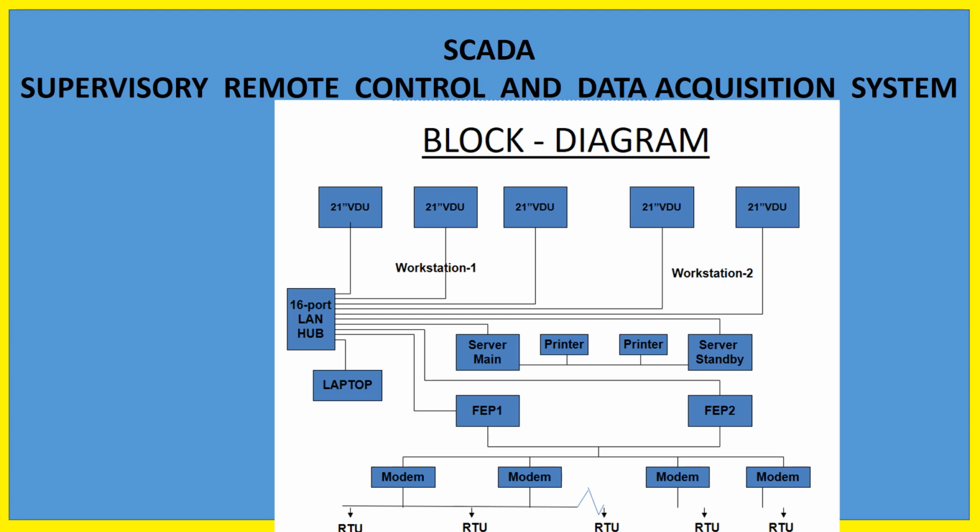This code is a DC signal with little energy, so it cannot travel to the end. So what we will do, we will modulate it with some carrier wave which has good energy, so that it can carry up to the end. After modulation, we'll send it through the OFC communicating cable to the particular post. It will read it by its address, and accordingly it will do its work. Suppose the command is to open an interrupter, then it will open it.